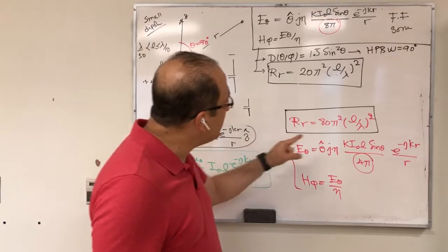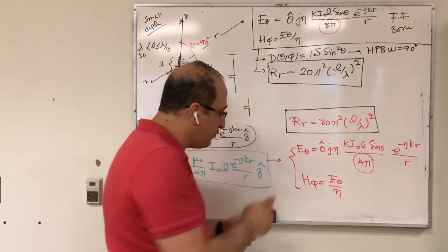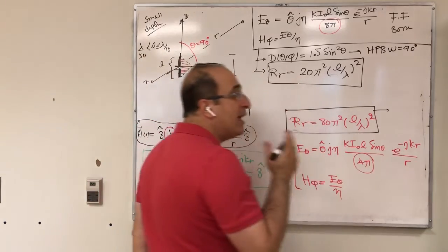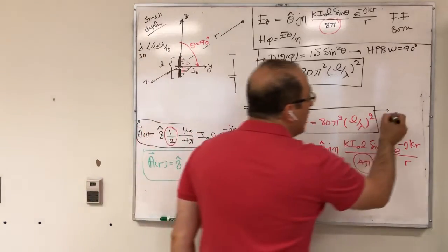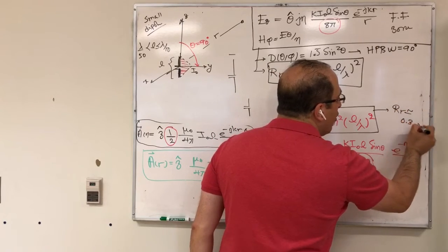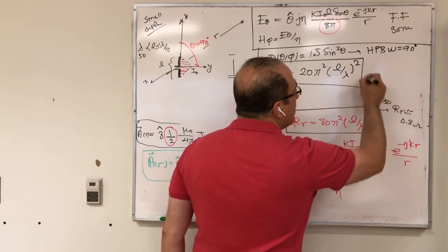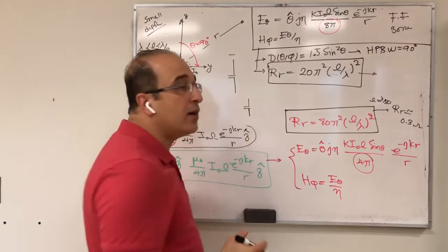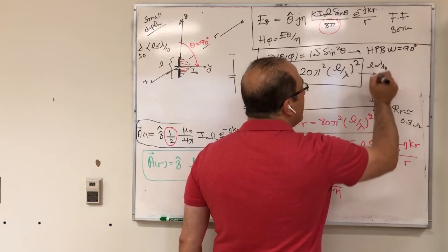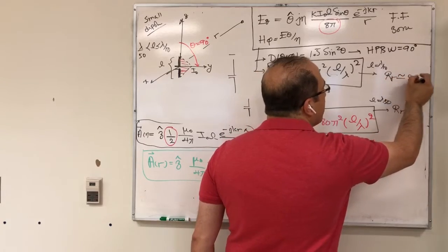But in terms of the actual value, that's not the case. Because in this one, for the infinitesimal dipole antenna, you need to substitute L equal lambda by 50, and you get about 0.3 ohm. So this is L equal lambda by 50. But with the small dipole antenna, L could be lambda by 10, so you substitute lambda by 10, and you're going to get R_R, which is around 2 ohm.